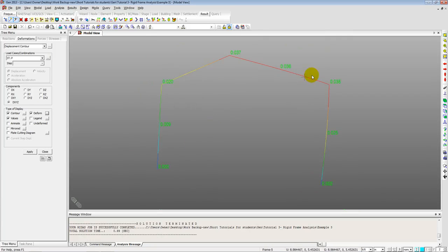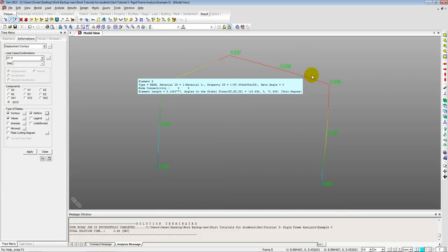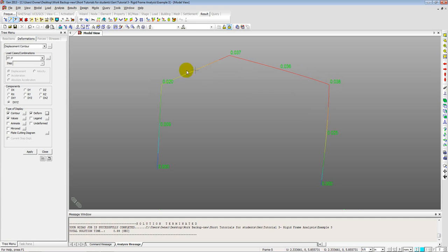Okay, so deformations depend upon the section's shape. So it will change if you change the section shapes or material properties, material elasticities. So this property as well as the stress property will depend on the actual dimensions of the element. The other things like forces in a statically determinate structure will not depend on the member properties.